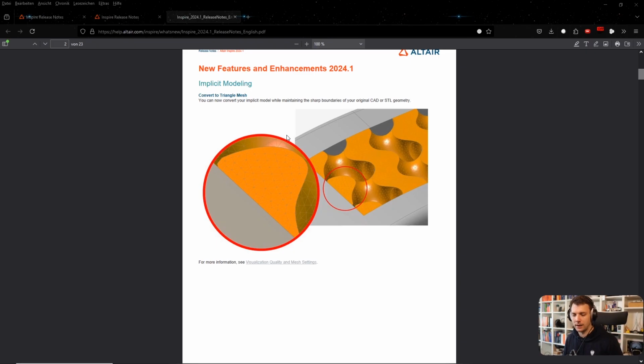This is in particular helpful when you have a design or geometry which is created by rules, for example, for a heat exchanger. You could imagine that you would do the geometry by yourself and sketch every line and every little fin by yourself, but it's not really efficient. A more efficient approach would be to just state the rules how geometry should be created.